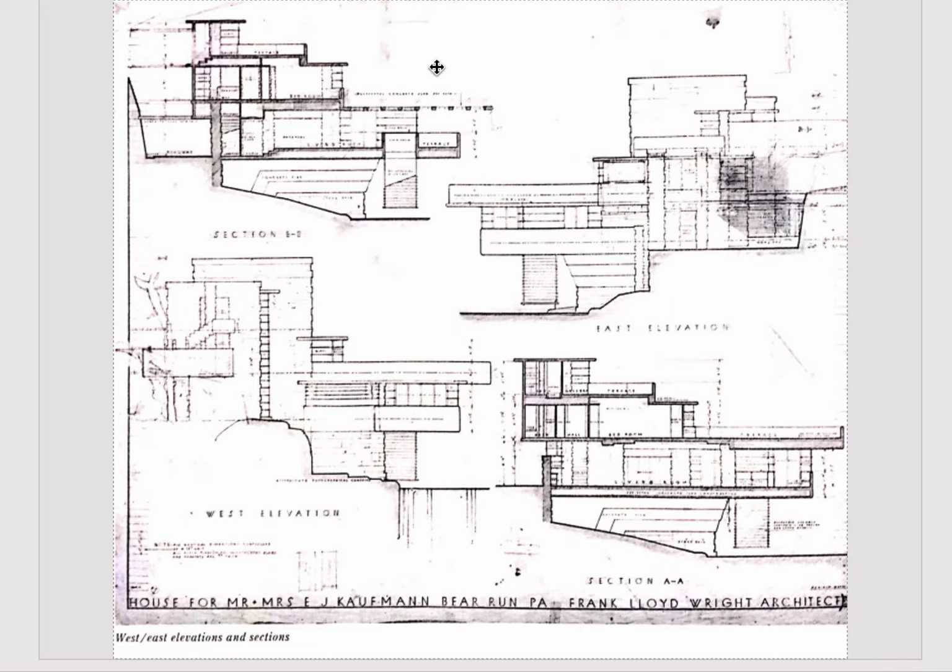This is a section through the building. And this is another section. So those are the cut lines. They're showing that it has been cut through. In this case, we're not cutting through anything, so the lines are not as bold. We're just using the visible lines. But you see there's an outline. The darkest line is around the outside of it, and it keeps going around the outside of the building. Okay, so that's the difference. And then the different features are next. Things that change planes, those are next, right? We have cutouts. Those are the same as the features that stand out.